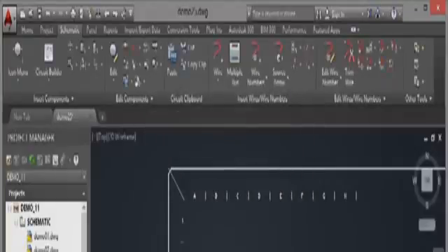So what happens now if I place a ladder, let's say? Can I place a ladder in a drawing that uses an XY grid? Well, let's go and have a look and see. Insert ladder. I can still insert a ladder, no problem. Width is 4.5, spacing 0.75. And let's go for, I don't know, let's say 10 rungs. Press tab, that'll work that out for me. I'll leave it as one phase and draw the rungs yes. Click on OK.